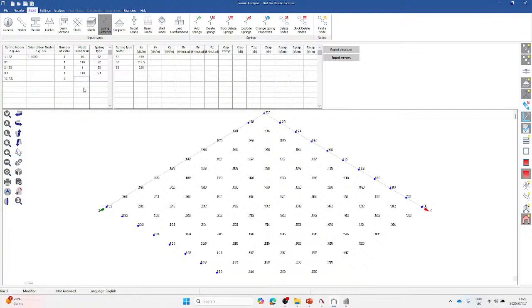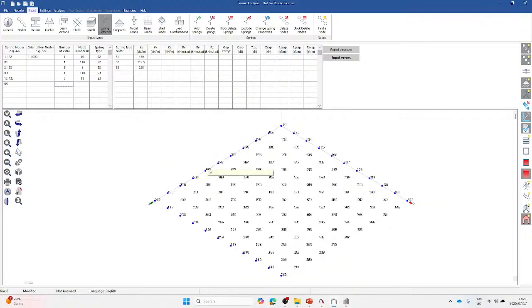And then node increment should be 11, and then that is S3 as well. Now we're going to block copy line, that's line 5, and we're copying these spring elements to this side of the slab. So let's just say one copy, and then that should be 10 increment, and that is S.